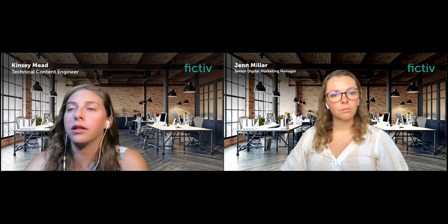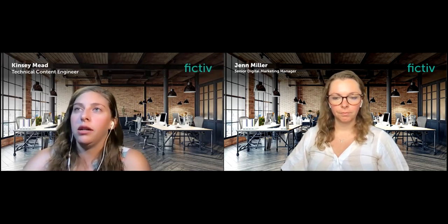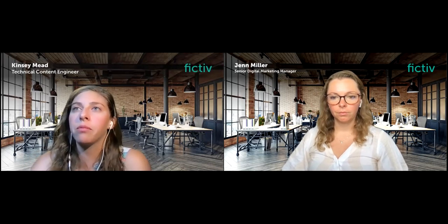Which is better, giving a datum on the base face, or mentioning profile tolerance and flatness and referring to that as a datum? That's a good question. That gets really in the weeds of GD&T. You're always going to define your datum surfaces first because that's where you're constraining a part and measuring from there. New feature request: use AI to predict design intent. Wouldn't that be nice? Incorporating GD&T into AI, I like it.